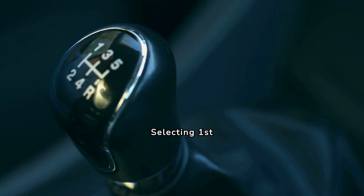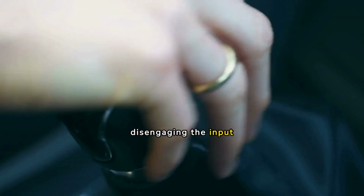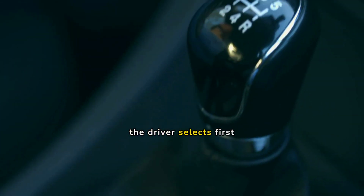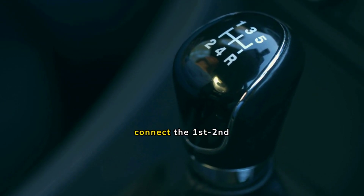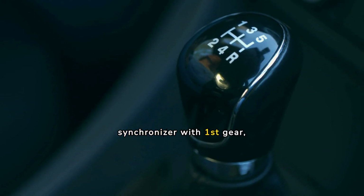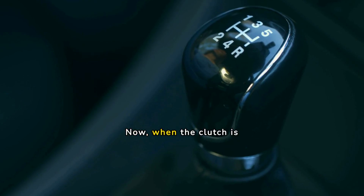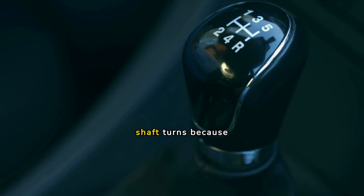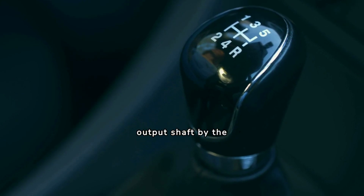Selecting first gear. The driver depresses the clutch, disengaging the input shaft. Using the shift lever, the driver selects first gear, and the shift rod moves the shift fork to connect the 1 and 2 synchronizer with first gear, locking it to the output shaft. Now, when the clutch is released, engaging the input shaft, the output shaft turns because first gear is locked to the output shaft by the synchronizer.